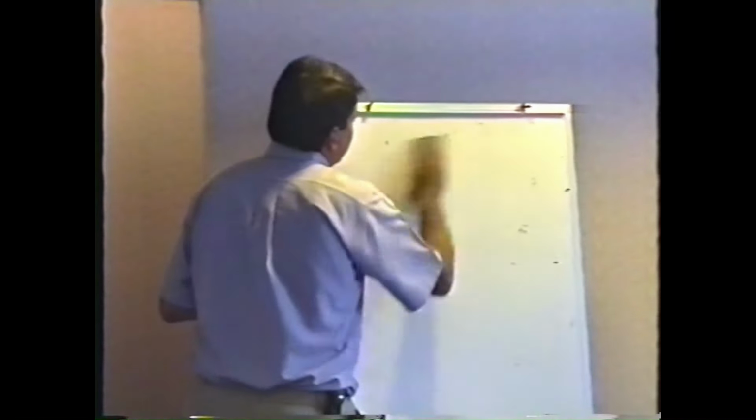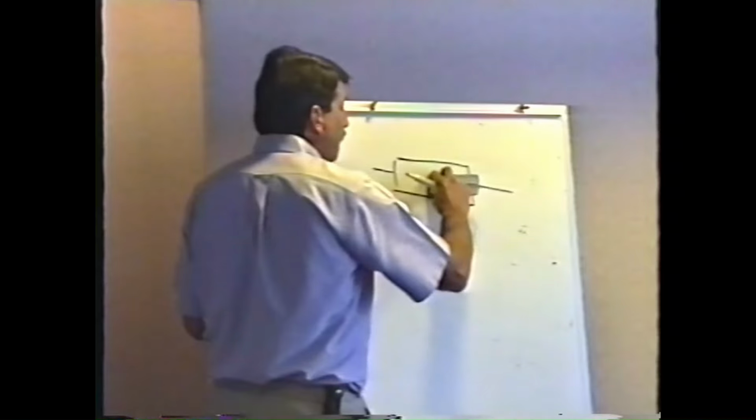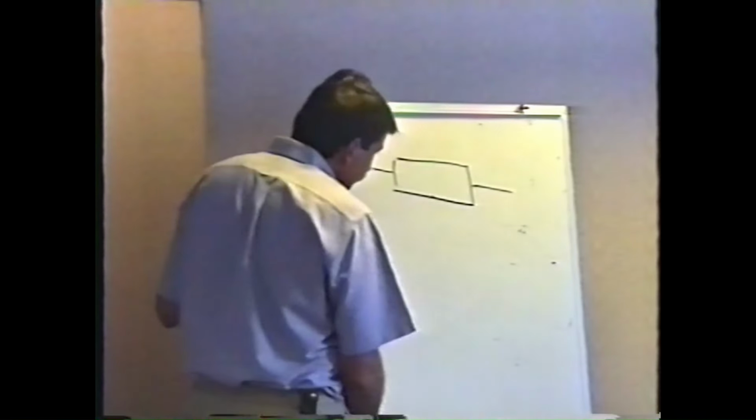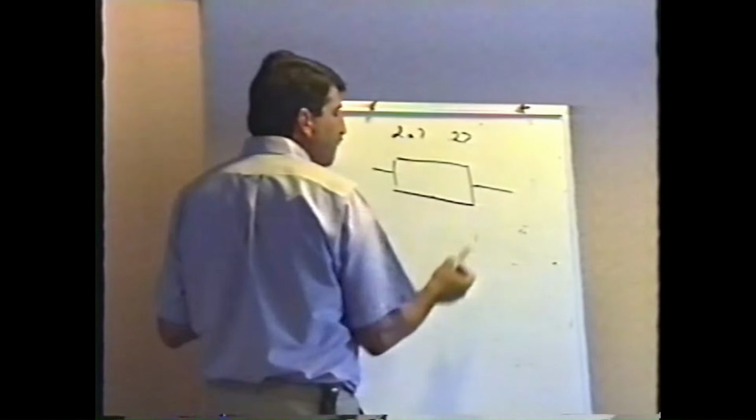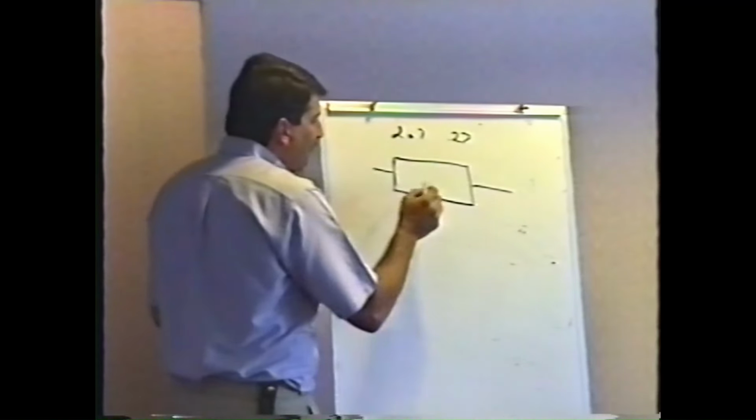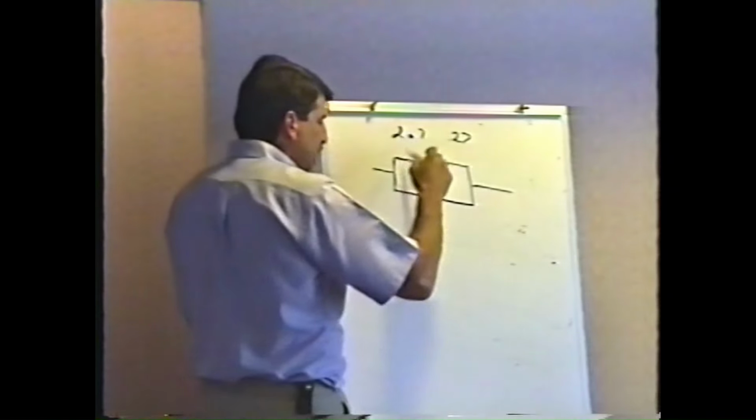The first band of a resistor is never black. That is, it's never 0. You would think that if we wanted to have a resistor that was 1 ohm, it would be like black, brown, black, wouldn't you? But it's not. For some reason, I have no idea why, the first band is always brown or higher. That is, it's always 1 or more. But we have resistors that are fractions of an ohm, like maybe 2.7 ohms or 0.27 ohms. We have another way of showing you which value is which.